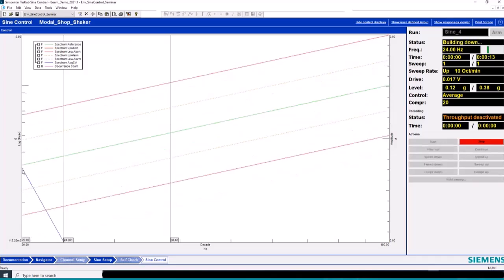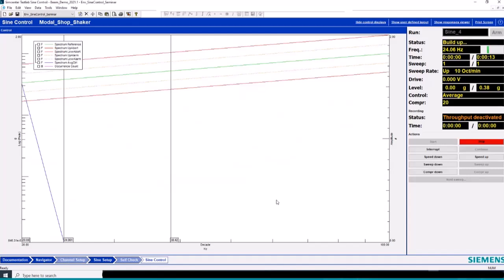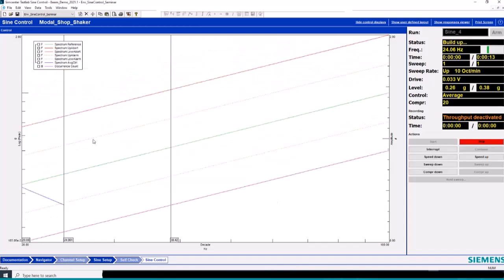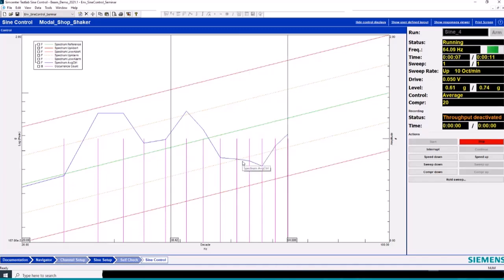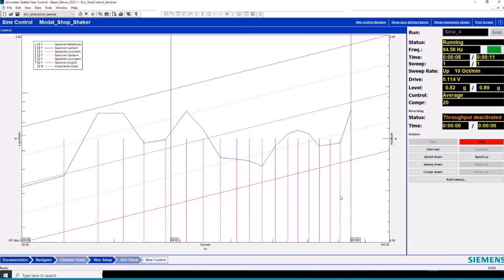You can see immediately with those setup parameters, I am aborting. I'm way outside these minimum abort limits. It's got an update to the transfer function at this frequency, at this occurrence count. So I am going to go ahead and resume and see what happens. So it's building back up. It's going to have an updated transfer function. It gets to that first line, and you can see by the time it does a loop closure, it is stepping up quite crudely in frequency.